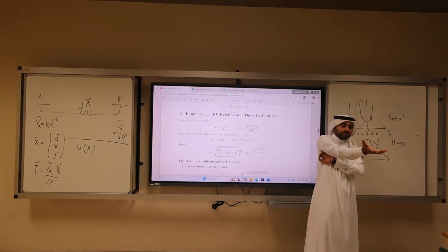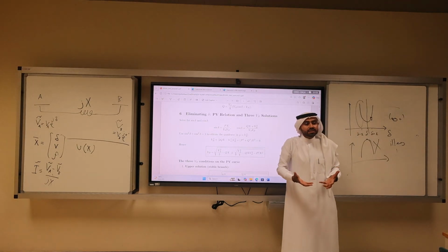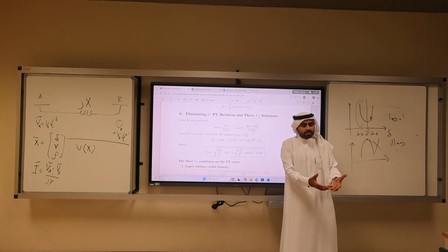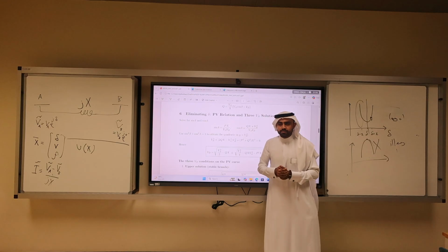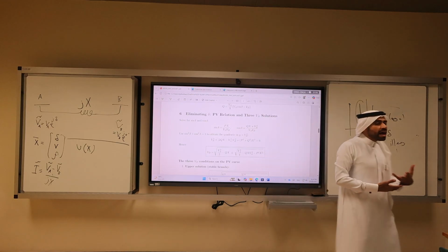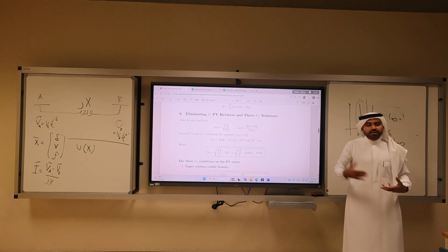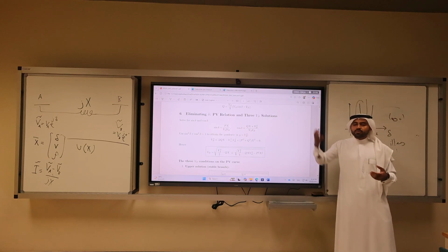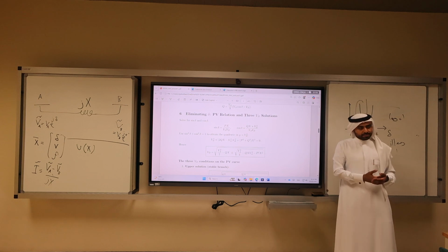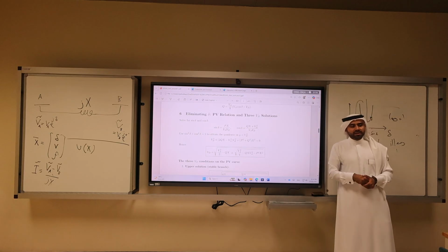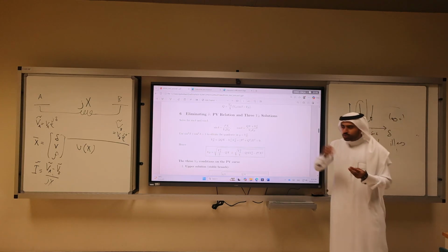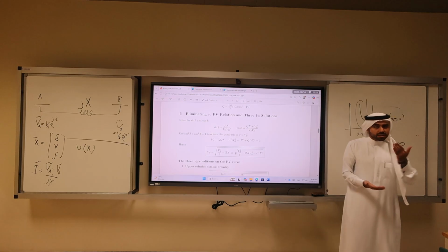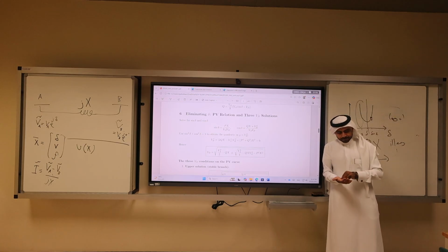Because you can't measure it. You can measure it with lasers, but if you are measuring the power in the system, the power flow can tell you the story without dealing with the delta. And in state estimation, dealing with angles is much more difficult than dealing with the real power. Remember, when real power moves from A to B, there is money involved. If there is money involved between utilities, then there is no way the two of them make the same mistake. So that's why in power systems, the power flow from A to B is usually quantified, and the utilities know how much power is moving from A to B.